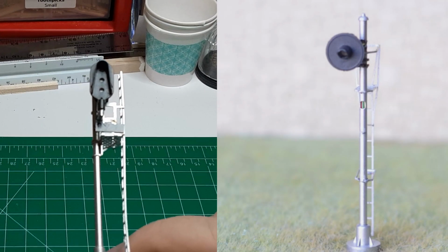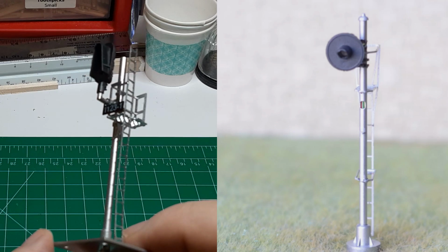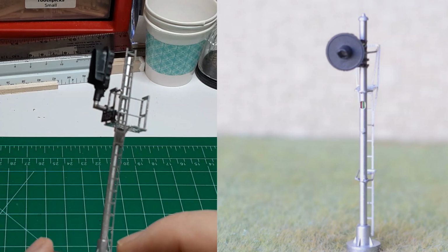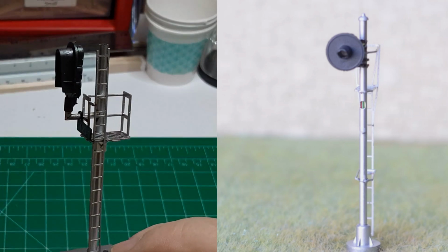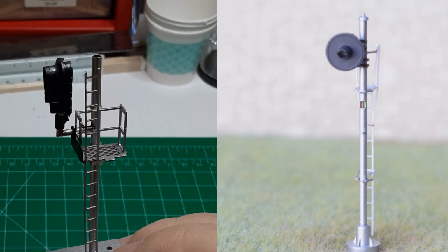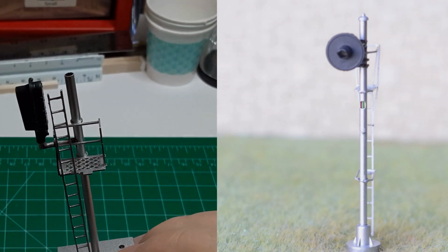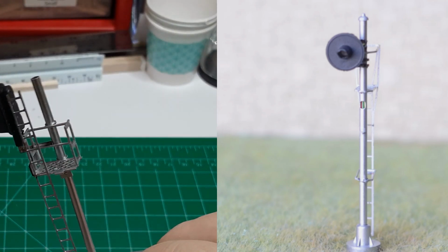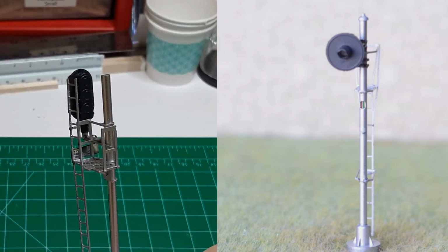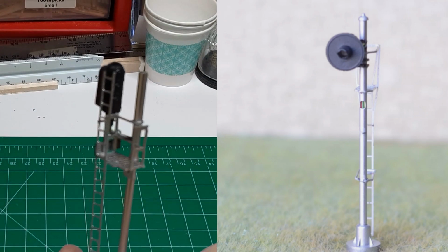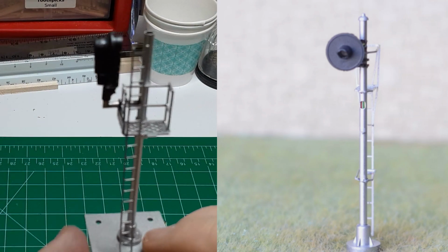Here are two examples of single-head signals. The signal on the left is a Type D signal equipped with three separate LEDs, one green, one yellow, and one red. The signal on the right is a Type SA searchlight signal with one lamp which can display green, yellow, or red. Since this particular searchlight signal uses a three-color LED with four leads, these two signals are electrically